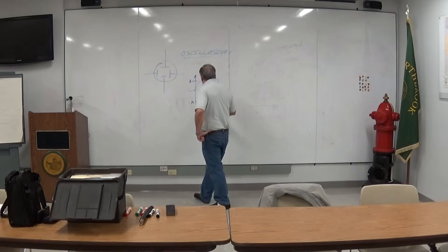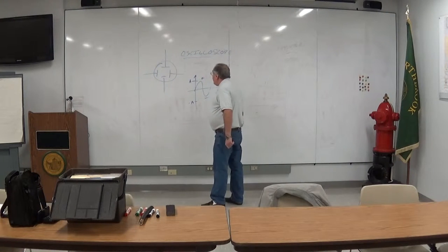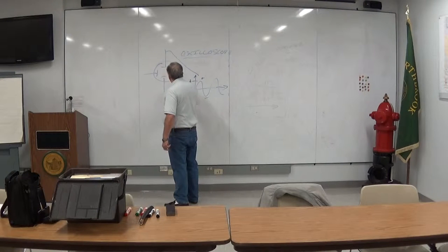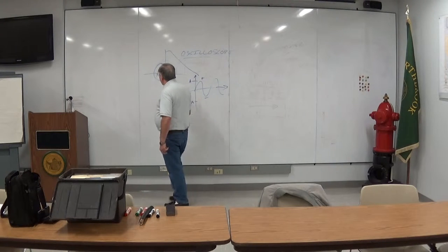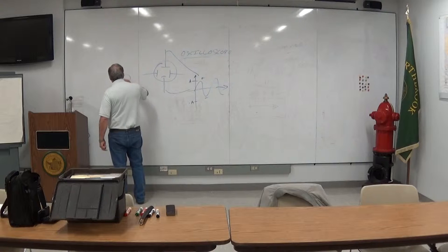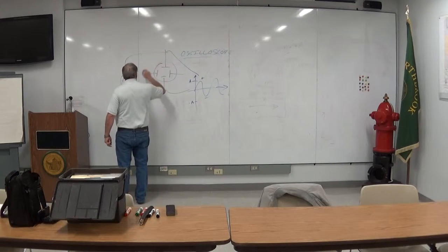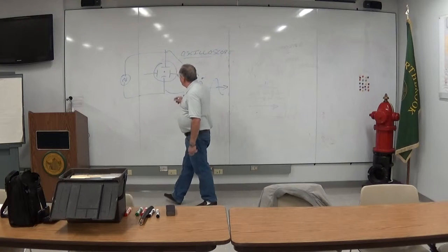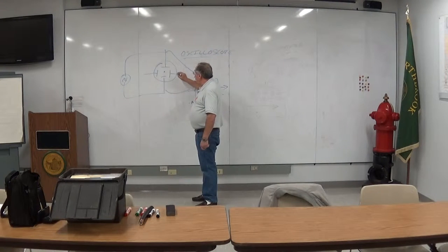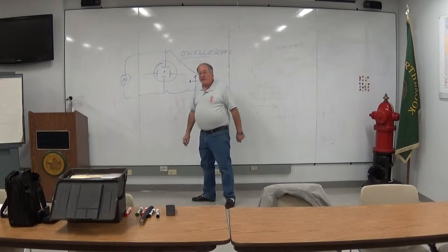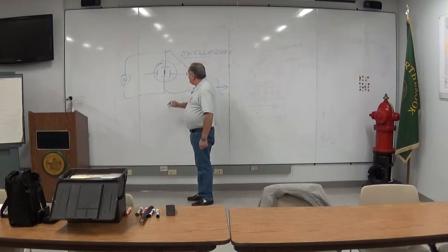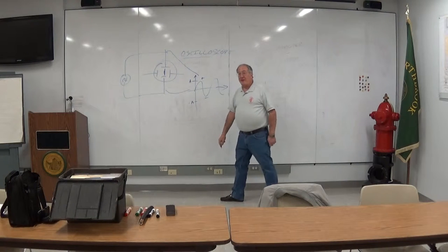and minus, and this is over time. So we feed this signal into the vertical plates. Basically, if I've got an AC generator, that's where it goes. It makes the beam that is emitted from an electron gun and hits a phosphor screen and produces a dot there. It makes it move up and down in correspondence with that waveform.